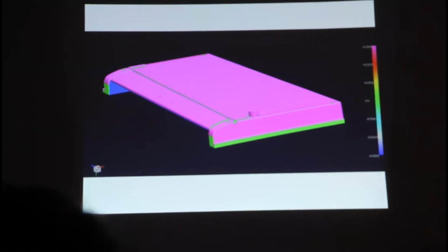Okay, what is important in this stage is to know where the dividing plane will be. None of the plastic part should be behind a corner, because you have to take it out of the mold, and nothing can be hidden behind the corner.